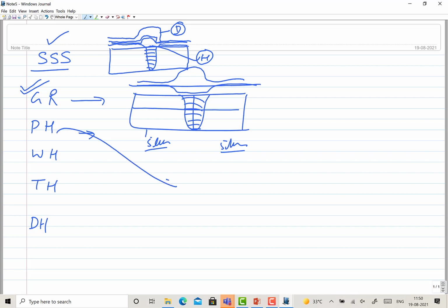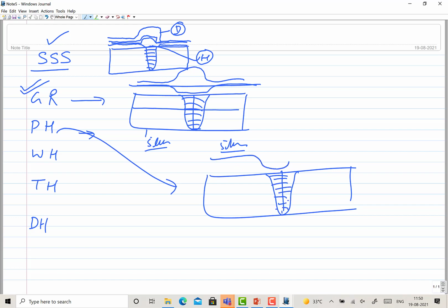In precipitation hardening, typically what we get is that your precipitates are usually lost, and that is the main thing. So sometimes despite refinement, you get a drop in hardness at the joint. Okay, and if the precipitates have got lost, invariably we get a dip like this. So your strength is getting lost in the weld zone. So failure will be occurring from the weld zone only, not from the base metal or the heat affected zone, because your precipitates have been lost.